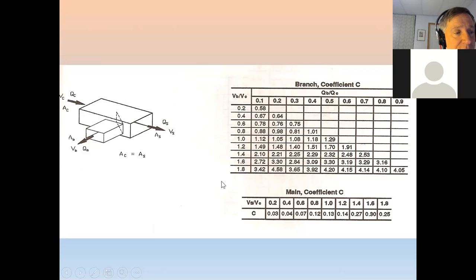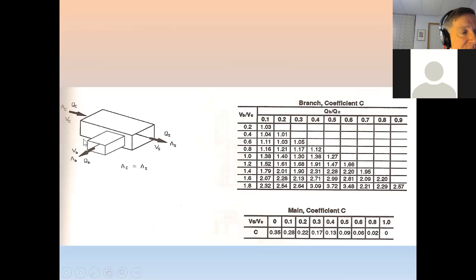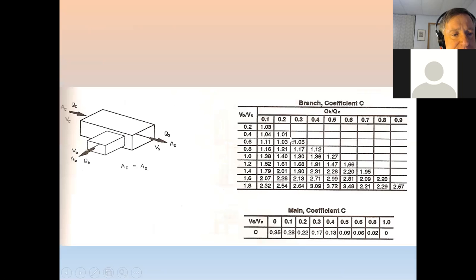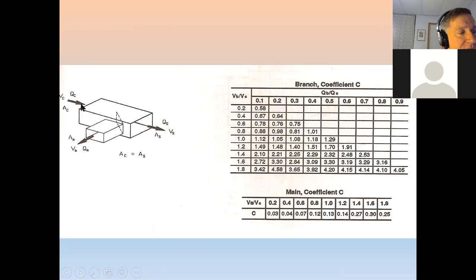And I'll show you another. This one here actually has an extractor, and you can see how it's got the turning vanes or the extractor. So these numbers down here should be lower. Yeah, you see these numbers are bigger. If you're trying to get air out of here, air hits this turning vane or extractor, and it makes it turn. But there's a bigger loss going this way because you got this sheet metal in the way.